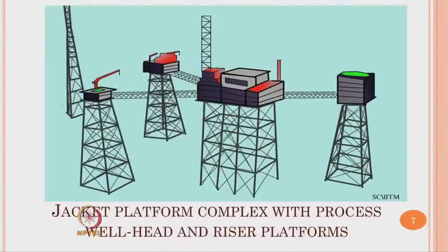platform, and let us look at the geometry or the structural form of these kinds of platforms. Why they are called template structures is for a simple reason. The bottom supporting system, as you see here, comprises inclined or vertical members.